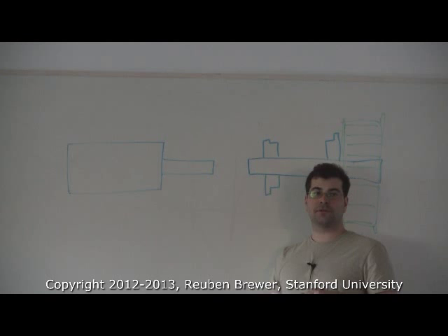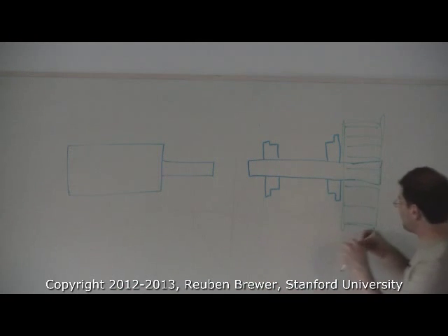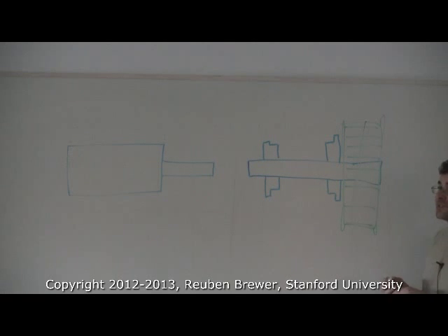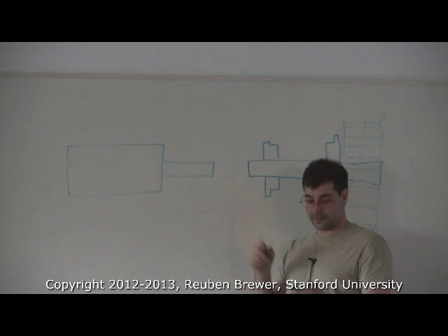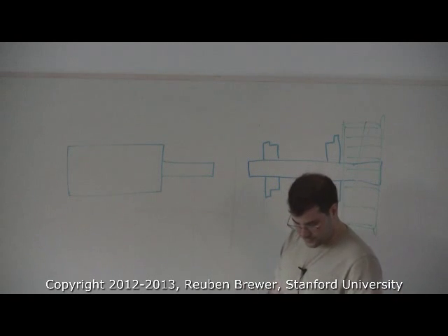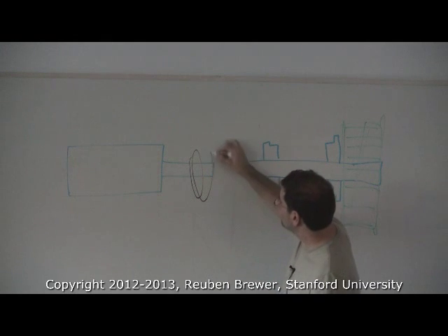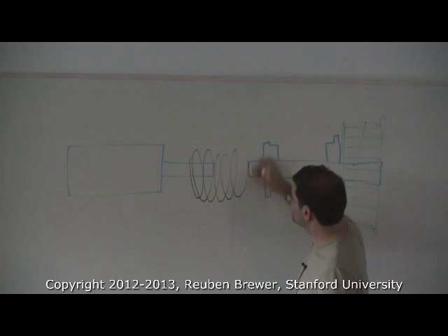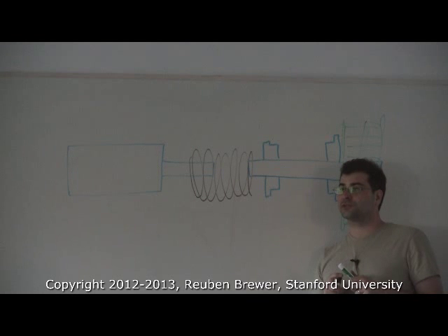It'd sort of defeat the purpose of being able to take the motor and the encoder off. You know, say we have a belt coming off of this and I really don't want to disassemble it. So I'm not going to weld anything. It needs to be temporary. The gold standard of doing this is to use a flexible shaft coupler. So it's essentially a giant spring. It is low stiffness in flexure and high stiffness in torsion.